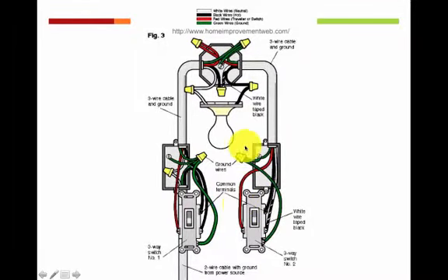As you can see here, this is what could be a typical wiring setup for a typical three-way circuit involving one light and two switches. I have one of these in my kitchen, and I also have one of these in one of my bedrooms, because you can actually access the bedroom from two different locations. And mine is very much like this. When I moved into my house, all my three-way switches were wired wrong. So you could turn one switch on and it would turn the light on. You turn the other switch and the other switch would turn it off.